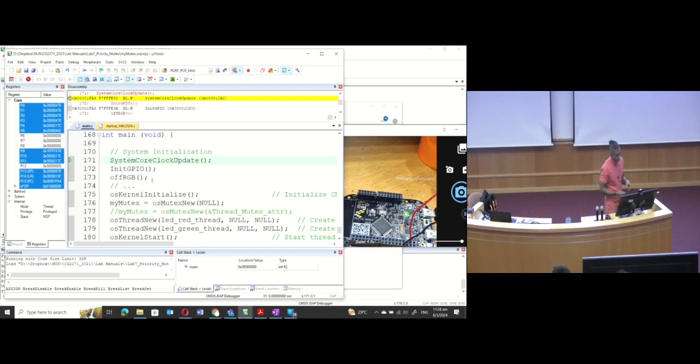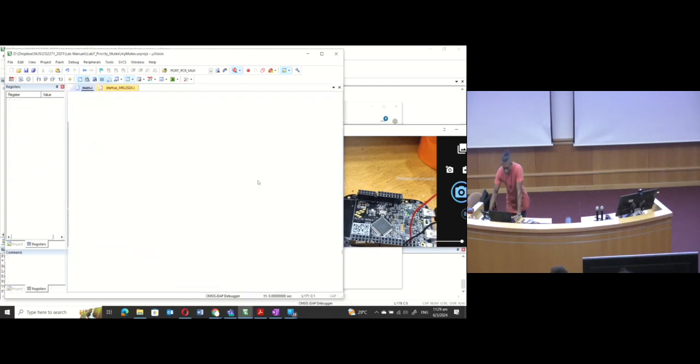So that is the mutex. You can see that you can have a few different scenarios even with mutex, if you use it correctly, or if you use it incorrectly, with one task totally not using the mutex, or using it partially. So that is mutex. Now let me show you the semaphore also, so you understand how the semaphore concept works.